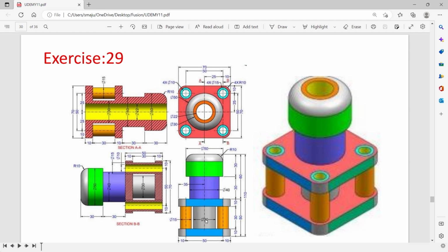So what we'll do is we'll make some concentric circles, and the circles will be having diameter 50 mm, 40 mm, 30 mm. As this is a hollow one, so inner one will be actually having diameter of 22 mm. So we'll make 4 concentric circles of diameter 50, 40, 30 and 22 mm, and total depth of extrusion equal to 110 mm. And from bottom it will be extruded to a depth of 50 mm, next one 30, and again the final one also 30 mm, right? So accordingly we'll start sketching from the top view.